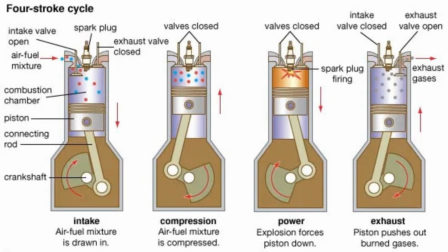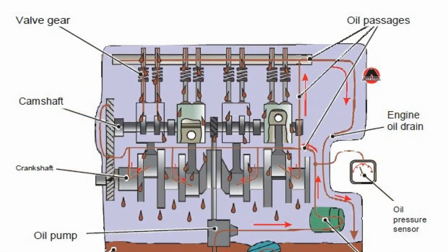Some models of power units are equipped with oil coolers, in which the cooling of engine oil occurs either by blowing a counter air flow or coolant circulating through the radiator tubes. Since the most widespread is the combined method of oil supply, it makes sense to talk in more detail about its varieties, already mentioned by us. Wet and dry crankcase. Wet crankcase. This method is commonly used because of its ease of implementation.